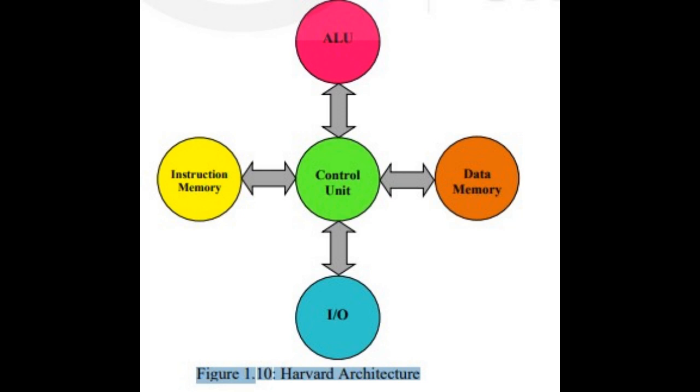We may store instructions and data together or separately. In the Princeton architecture, data and instructions share the same memory space. In Harvard architecture, instruction memory space differs from data memory space. Princeton configuration can lead to easy hardware connection to memory, as only one connection is required.